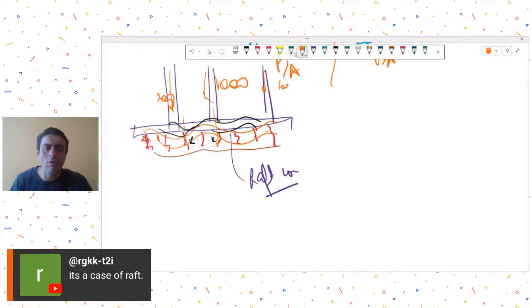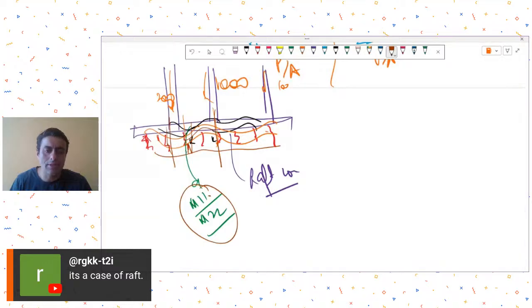What will alter more is the moments. So if you were to check your moments in your raft, more so than the base pressure, what is going to alter might be your moments in your rafts because of these unequal settlements or non-uniform settlements. Okay, you understood?